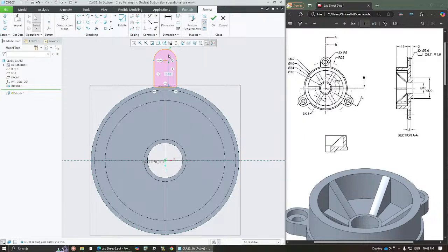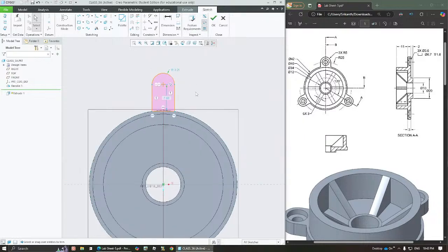Okay, so this is the shape that we wanted. Right. When we see the radii, it is 3 times of radius 5. So let's make it radius 5, and the distance of this has been at radius 25. So we can go with construction circle from here to center this.